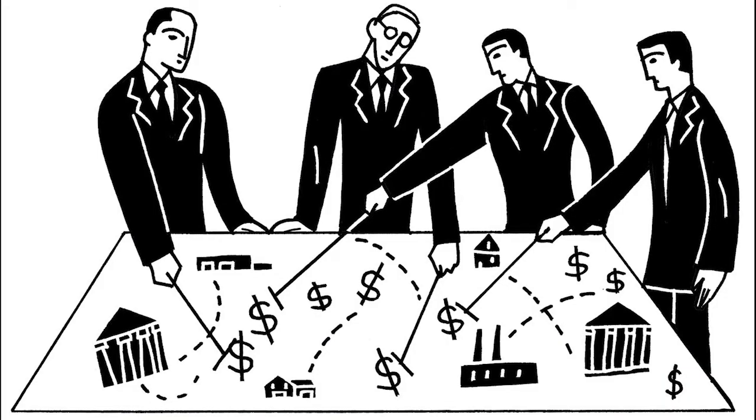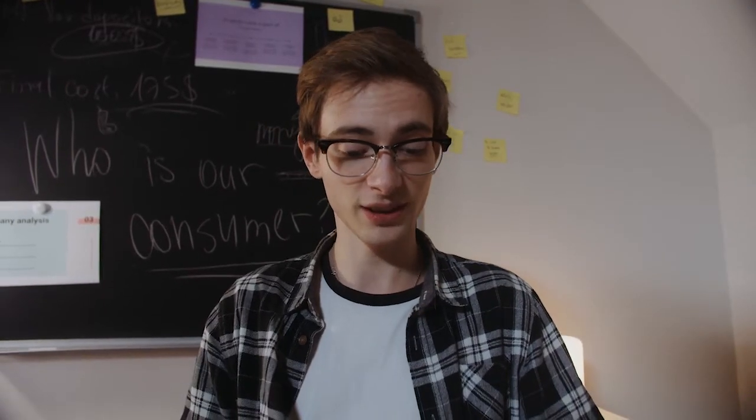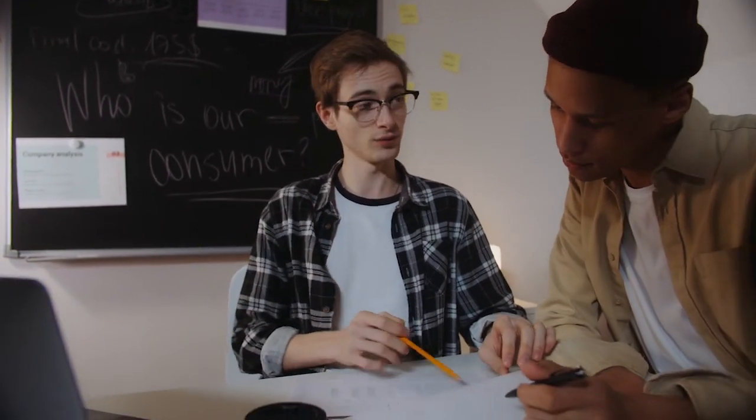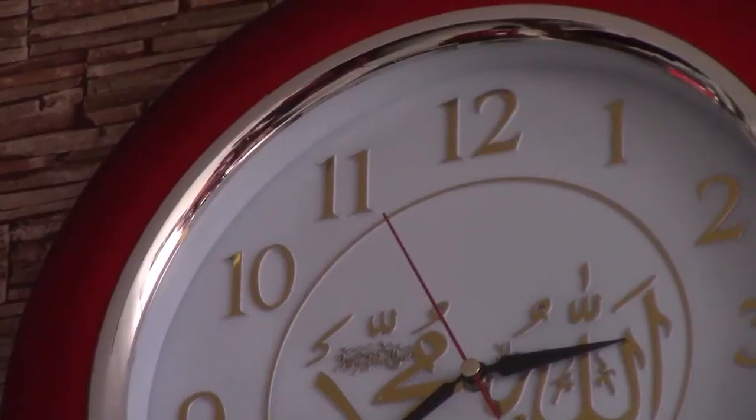One probable solution for a person who is thinking of the economy is to install a graduated size of pipe from say 30 to 100mm diameter in order not to violate the provisions of the code. The idea is very good and acceptable on the premise of economy. However, it should be analyzed carefully considering the cost of cutting different sizes of pipe, providing reducers and various fittings, plus the time delay and the high cost of labor. Otherwise, we might as well forget the idea towards unrealistic economy.